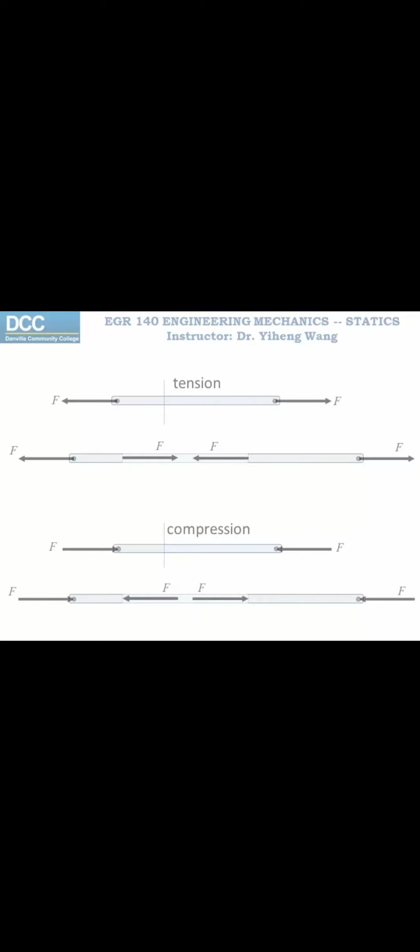The stress associated with the internal normal force, like the ones in the truss members, is normal stress, sigma, which is calculated as F over the cross-sectional area of the member, A, and it should not be greater than an allowable value. As you can probably tell, this is beyond the current statics class, but it is always good to know why you are learning what you learn.